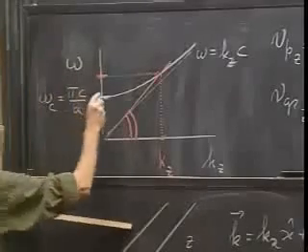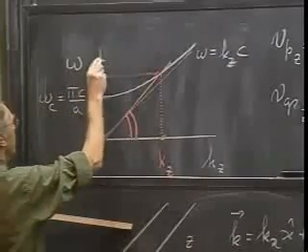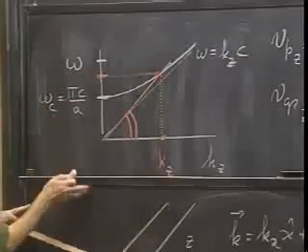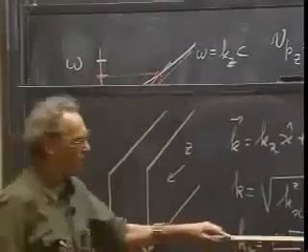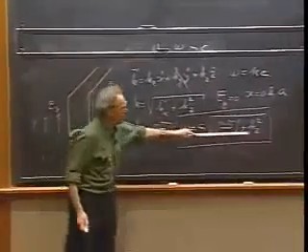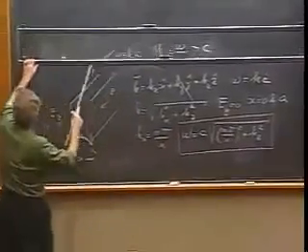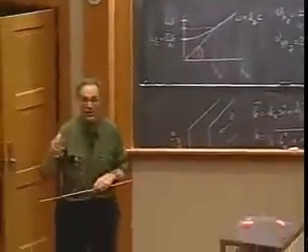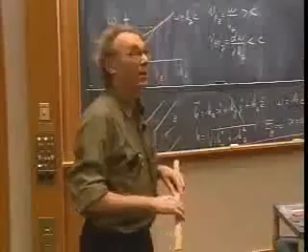If you go to very high frequencies, there is here another cutoff frequency, which is twice this number, because that is when m equals 2, and when kz becomes 0, that becomes twice as high. Then, of course, there are two different ways that you can propagate radiation in the z direction.